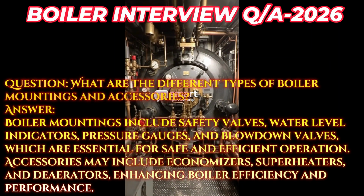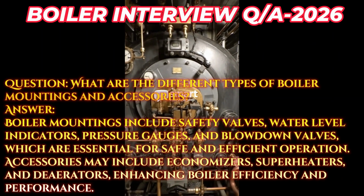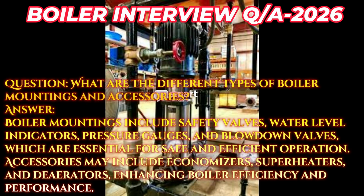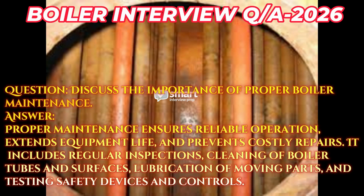Answer. Boiler mountings include safety valves, water level indicators, pressure gauges, and blowdown valves, which are essential for safe and efficient operation. Accessories may include economizers, superheaters, and deaerators, enhancing boiler efficiency and performance. Question. Discuss the importance of proper boiler maintenance.